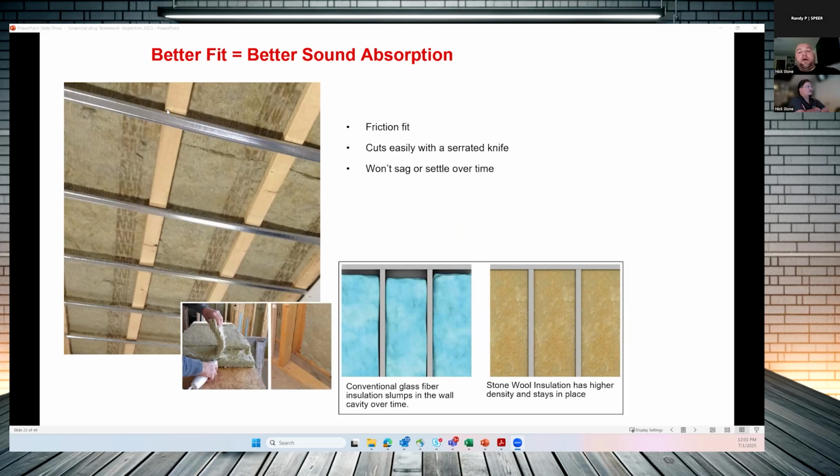So your standard two by four wall with our Safe and Sound product inside of there, the STC rating is around a 37, 38. Then as you add these resilient channels, that bumps it up to an STC of 47 by having that disconnect of the frame from the sheetrock. Now it's these resilient channels or mass loaded vinyl, something like that.